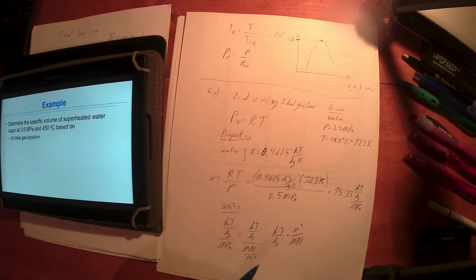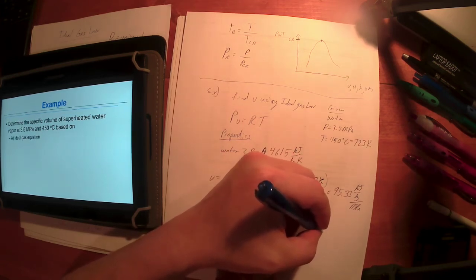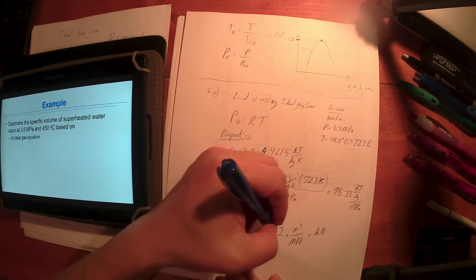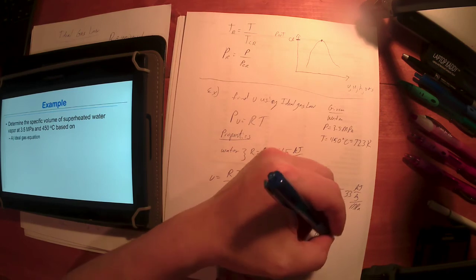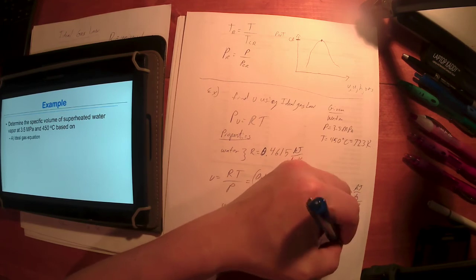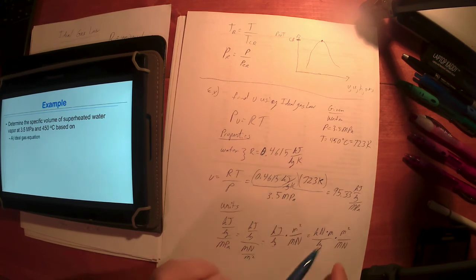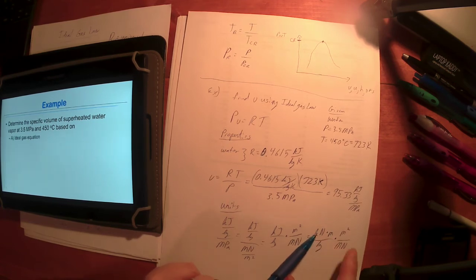All right, well, maybe I can break a joule down, right? What is a joule? Well, a joule measures energy. Energy is force times distance. So you can memorize a joule as a Newton meter, or you can remember this is force times distance because it's energy, so a kilonewton meter is a kilojoule per kilogram times meter squared per meganewton. Okay, now I'm getting somewhere. Notice the newtons go away, but I do have a kilo over a mega. So I'm going to have a factor of 1,000 there to deal with. But notice that if the newtons go away, I've got meters cubed per kilogram if I deal with the kilo and mega there.